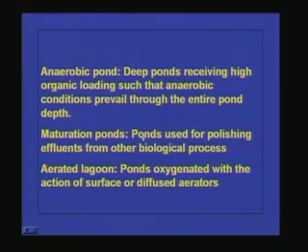So, the untreated organic matter coming to this system gets a long detention time, and definitely microorganisms will grow in the system. These microorganisms consume the organic matter left over in the effluent, and finally we get a clarified effluent. That is why we call them maturation ponds.